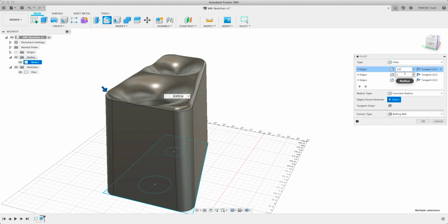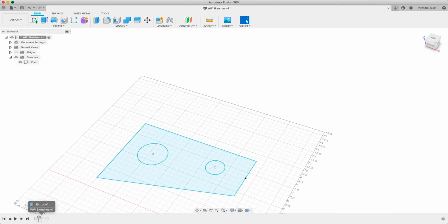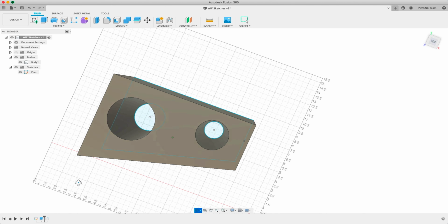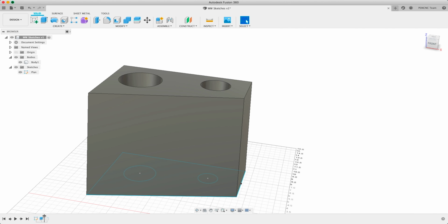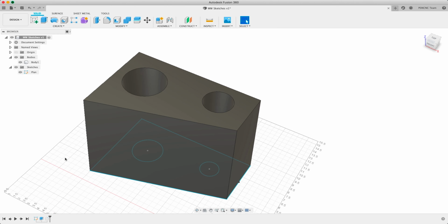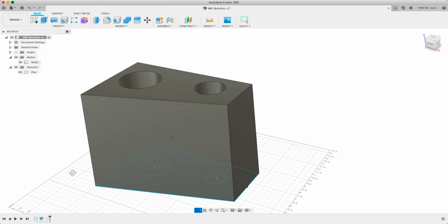So if that makes sense, essentially what I've done is, if we start over, make a sketch, extruded that sketch by going up to extrude. And anytime we make a change in this timeline, it's affected from the left to the right all the way through. So we've added these fillets, and maybe we don't want those fillets anymore. Just momentarily, we can right click, suppress the feature, and they're gone. So we can play around with this in a different way.